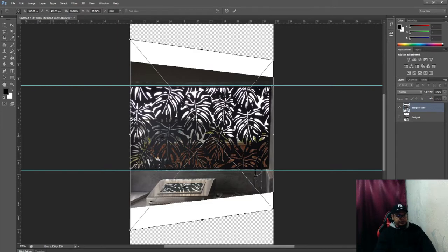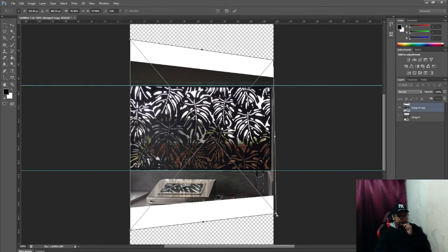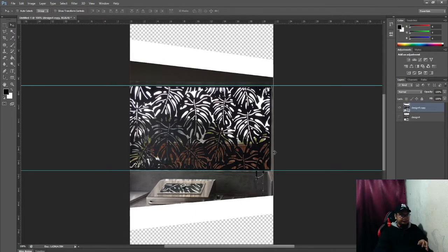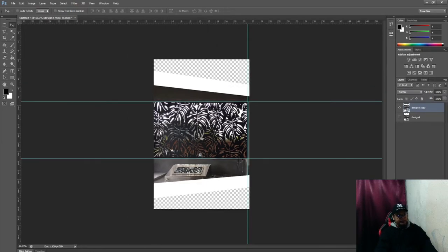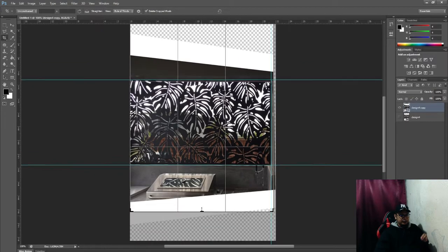Of course, we can choose other distort options here. You can check this one here, that is aligned object. Just try your best to plot the image. When we transfer this to AutoCAD, you can adjust the image, as long as here you just try your best to straighten it or flatten it, whatever you call it.